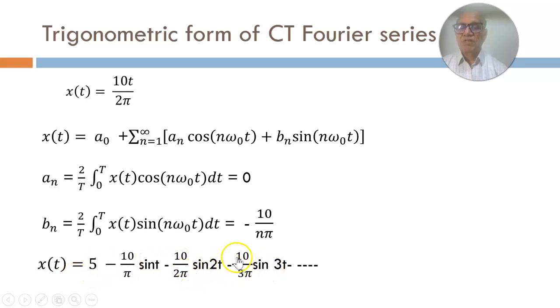And you have essentially obtained the amplitude of various frequency components. What about the phase? If you take sine as the reference, clearly the phase is 180 degrees for each of the components. That is the same, because there is no cosine component at all.